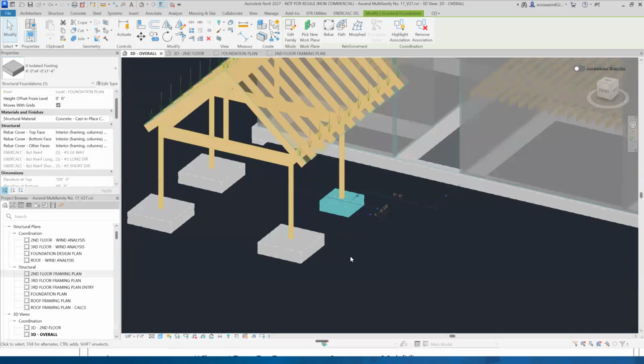That's right. And so when it comes to your engineered wood products, there is a mind-blowing level of diversity with how manufacturers specify their products, how engineers refer to those products, and how engineers and BIM teams like to build the types and families that contain those products. And so when you try to load a new engineered wood product, like a new LVL or a new LSL or something like that, we do not go fishing in the dark to try and find what you're looking for. We only load from content that's presently in the model if you're trying to load an LVL. So that's the one exception to that question.